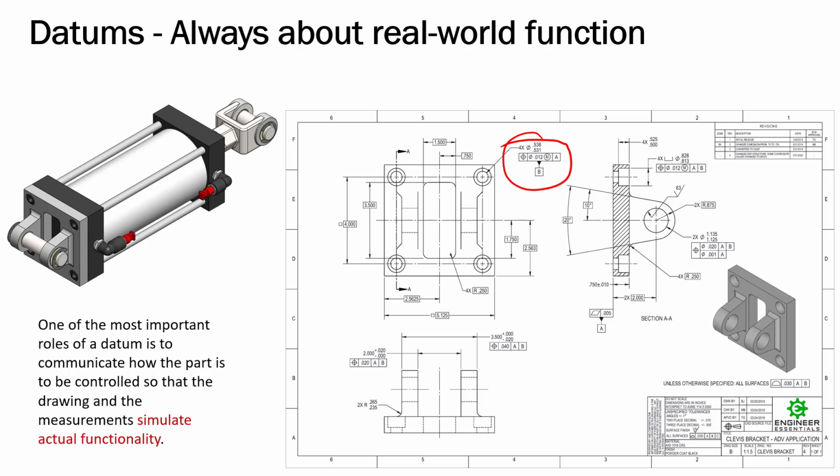And then when we go back and look at all of the datum reference frames that are used in the feature control frames, like I said, this position right here, we're telling quality that what matters for this feature is 3.5 inches wide with a tolerance plus nothing minus 20 thousandths. It has a position tolerance of 40 thousandths, but in reference back to A and B. So we want quality to lock it down on A and B.